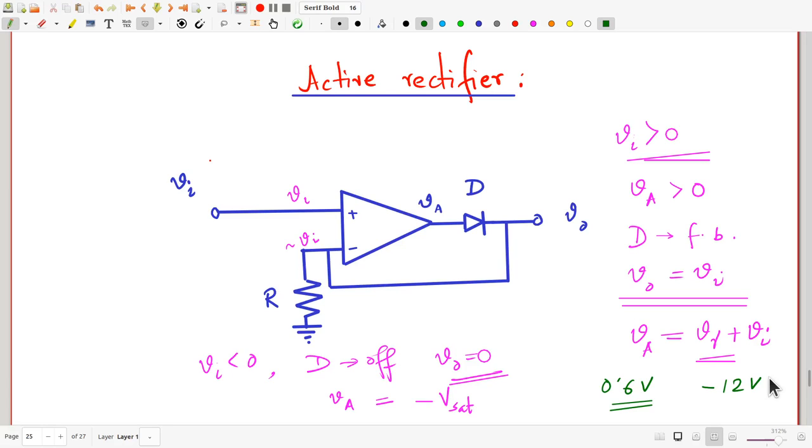So this circuit will work well enough for low enough frequencies, but for large frequencies, for which you might often want to use active rectifiers, this becomes not at all a tenable circuit to use. Of course, the 0.5 volts per microsecond limitation that I have talked about, the slew rate, is a slew rate for a standard op-amp that you can buy off the market. This is a typical value for the 741 IC, as I have been mentioning.